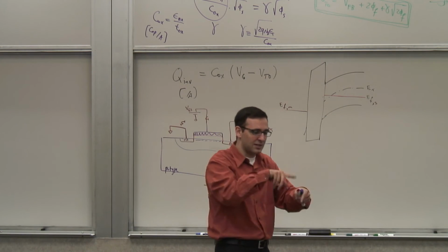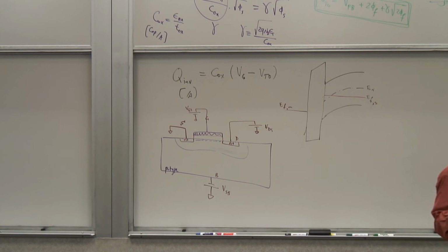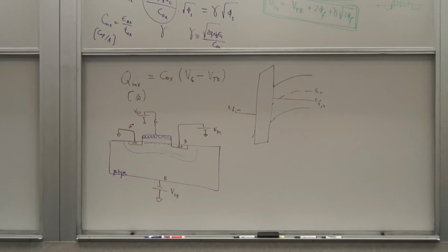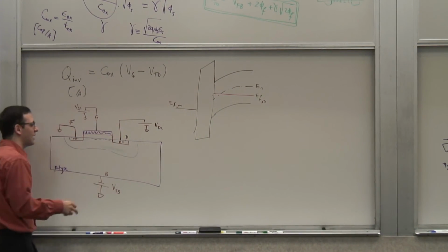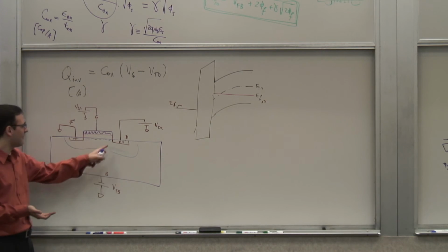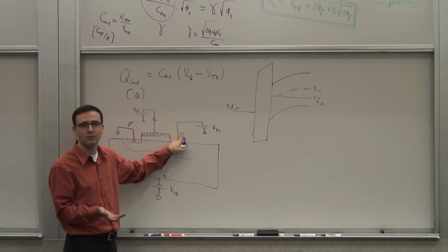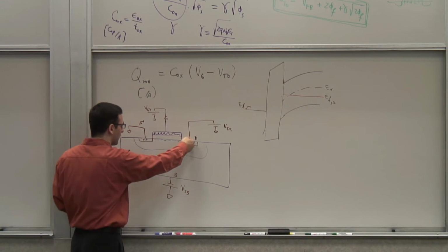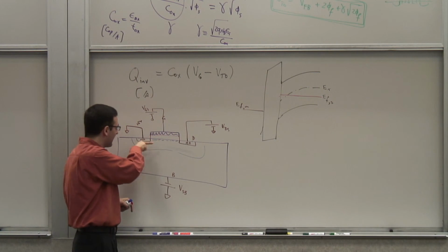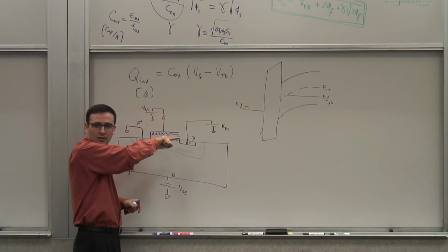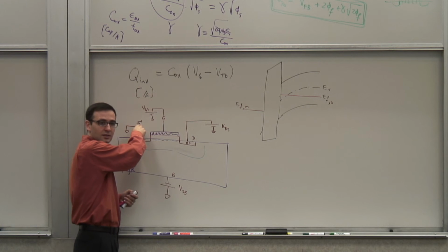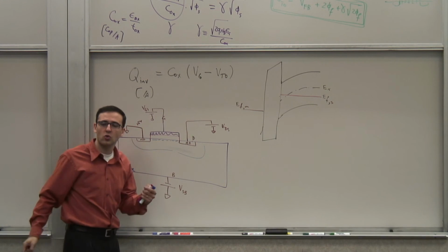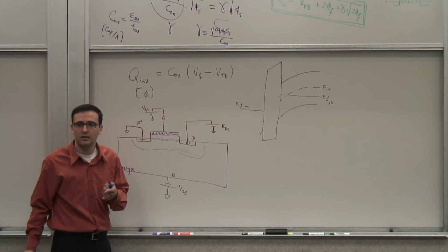So they're moving randomly, thermally, and every so often, basically, they're bounced off. And what happens is that when you apply the electric field, it shifts the mass, this electronic cloud, from one side to the other. Now, if I apply positive voltage, where would the electrons start and where would they end? If I have a small positive voltage here, let's say for now, the current will flow in this direction, right? Which means the electrons are flowing from left to right. Hence the name source and drain. So they're the source and the drain for the charge carriers.